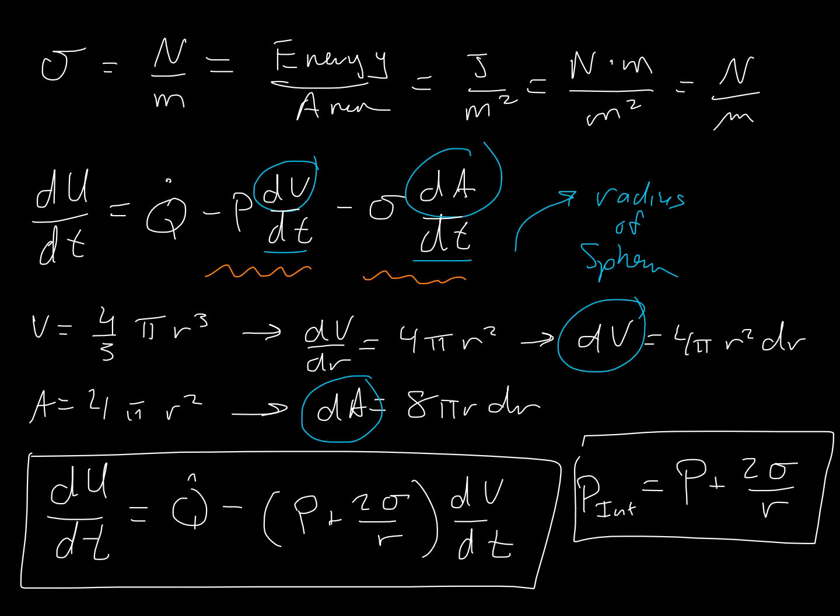So this term is always positive, which means that the internal pressure is always greater than the external pressure. This is the pressure of the system. So if I have an extremely small droplet, what ends up happening physically is that the pressure inside, which is basically the net force that the molecules inside are pushing across on the interface, is much higher than you would necessarily anticipate based on the external pressure.